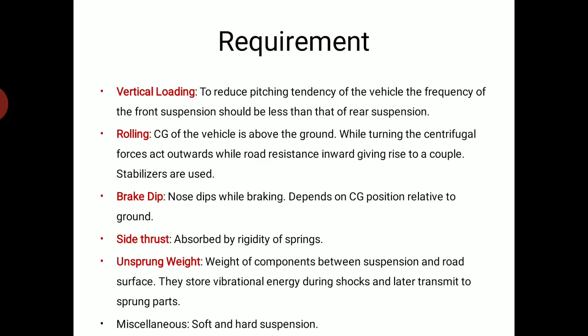Okay. So what are the requirements of suspension? There is vertical loading, rolling, brake dip, side thrust, unsprung weight. These are the different requirements of suspension. To reduce the pitching tendency of the vehicle, the frequency of the front suspension should be less than that of the rear suspension.